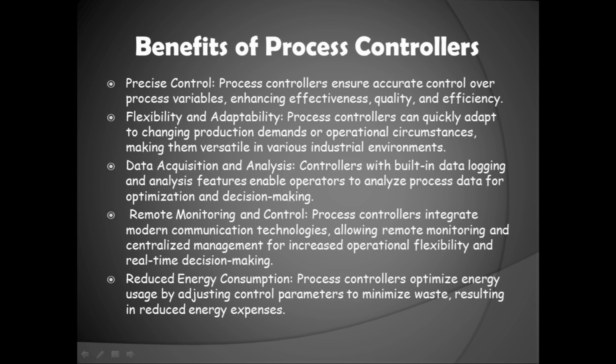Reduced energy consumption. Process controllers help optimize energy usage by maintaining process variables at optimal levels. By adjusting control parameters such as flow rate or temperatures to match the required demand, energy waste is minimized, resulting in reduced energy expenses.